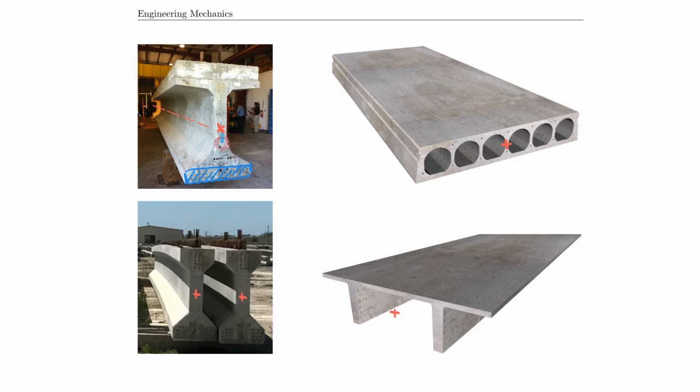Let me talk about the last thing here, again in reference to the rectangular section. Why is the rectangular section not a thing? So we remove material, and one thing that I talked about the whole time here is that we do this to remove the material from the centroid location. That is number one. But we also remove material, and removing material saves cost and saves weight.